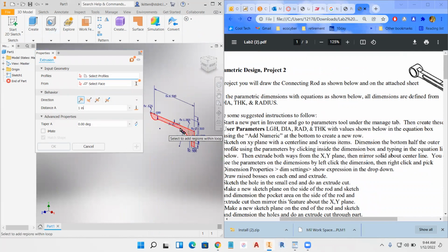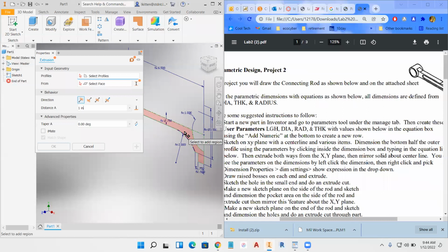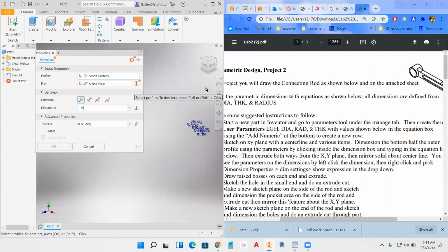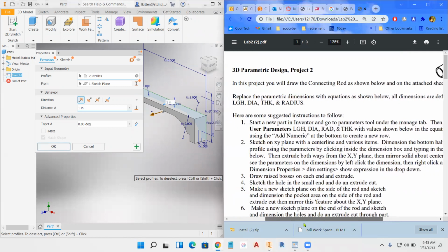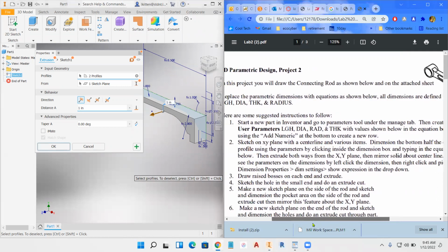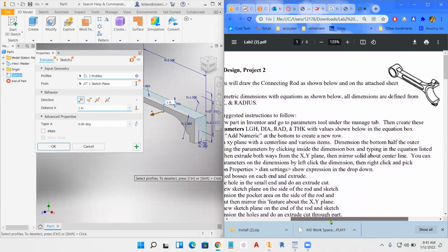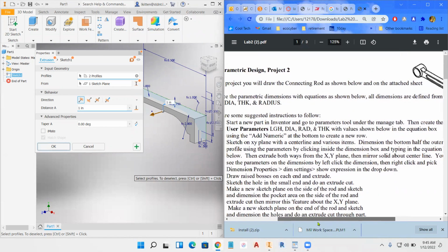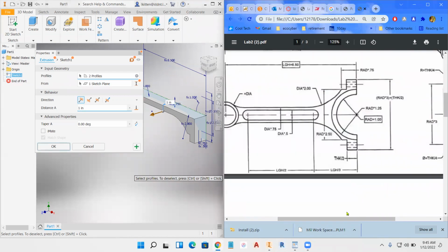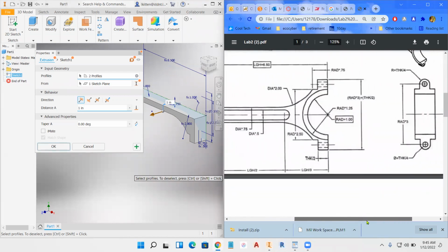I was thinking that center line wouldn't let it work, but if there's a construction line, it would ignore it, but a center line, it actually works. Okay, so hit finish sketch. Our instructions were actually right, believe it or not. Okay, and pick on that bottom part, okay? And then we want to extrude it the right distance, so we gotta be careful here. Okay, so it doesn't really tell me there. So I think it's probably the thickness, but let's find out here.